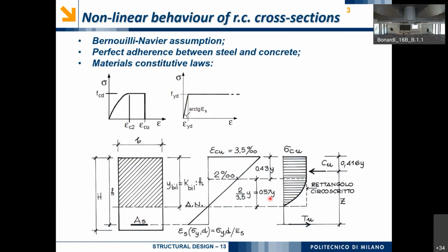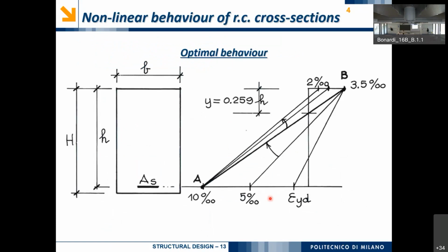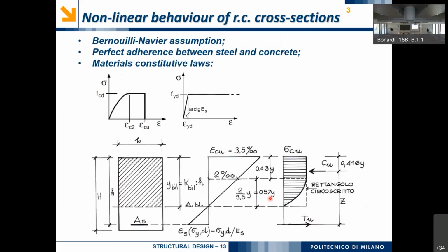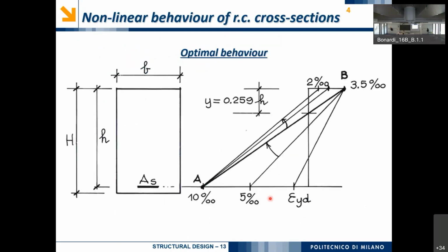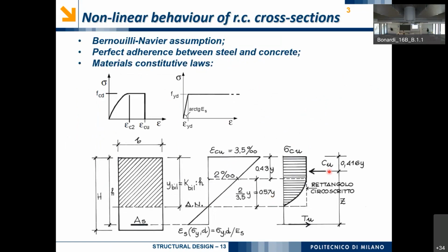So basically, we have this new model in order to tell us how the reinforced concrete behaves, and varying only the neutral axis will change the resultant compression force and the resultant tension force.